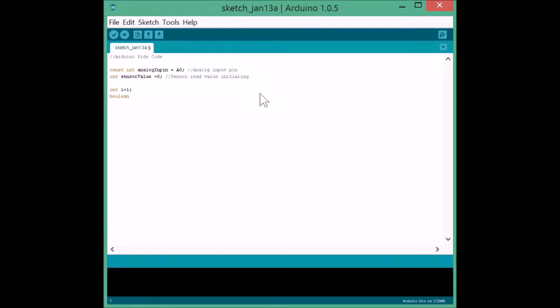Next I'm initializing the conditional boolean data, so that our Arduino knows when to send the data, because it's completely unnecessary to send data all the time. It would be a waste of time and energy. This is the condition we'll be using after we get an acknowledgement that the connection has been established between the Bluetooth module connected to the Arduino and the Android smartphone.